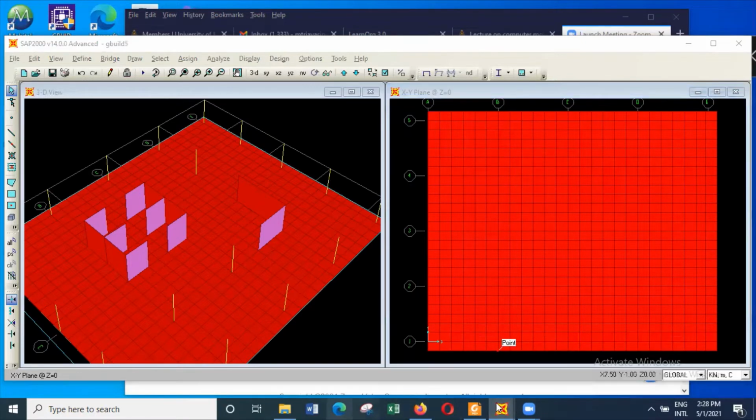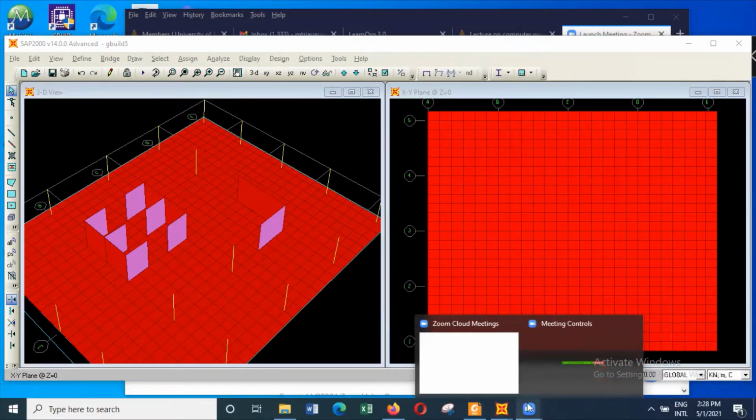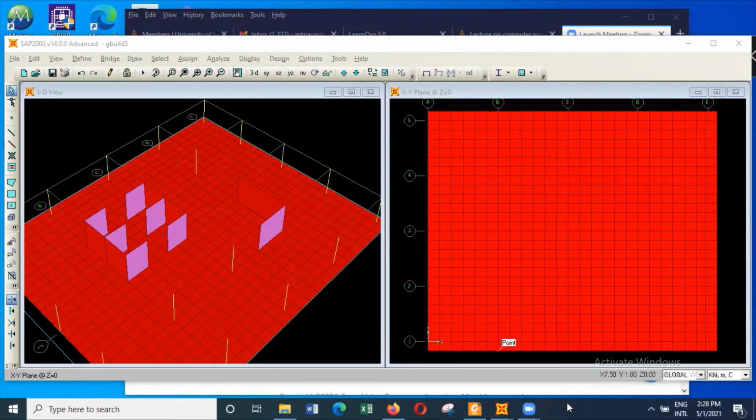is to use the formula that K is equal to factor of safety multiplied by the allowable bearing capacity multiplied by 40. The vertical subgrade reaction is given by factor of safety multiplied by bearing capacity multiplied by 40. These are all in your notes. But to represent this raft with springs, we have to multiply this by the area represented by each spring.